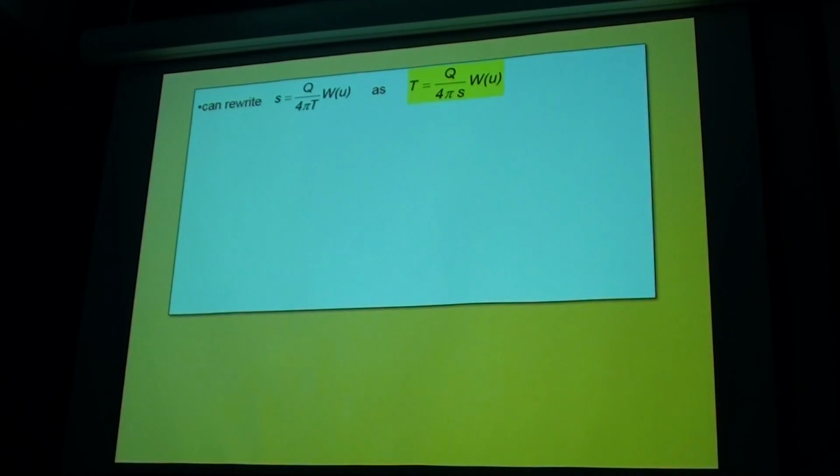It was really good. Okay, so you can rewrite this thing as this, because we want to work out what T is. Okay? We want to work out transmissivity. It's one of the things we want to get from our aquifer. We're going to know what this variable is, we're going to have to find out what this is, and this is a variable. We have to find out what this is. But we're going to do this by a little tricky graphical method that Theis worked out, which is what your computer does in the background.